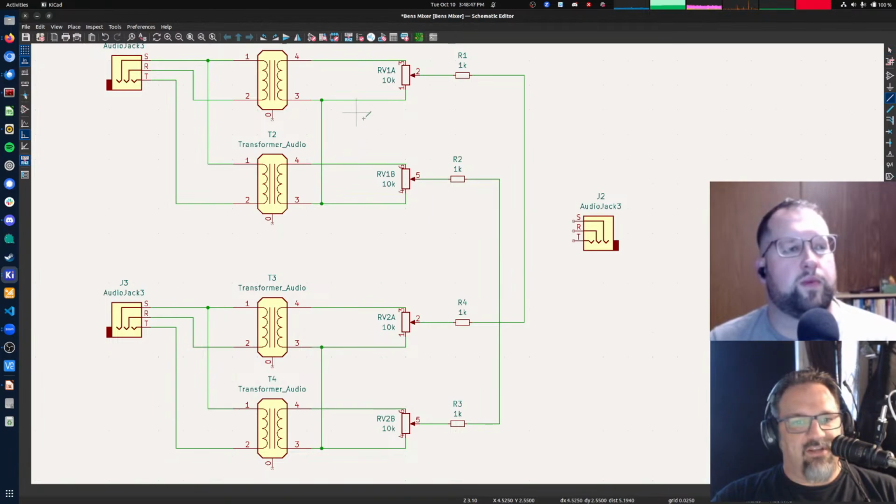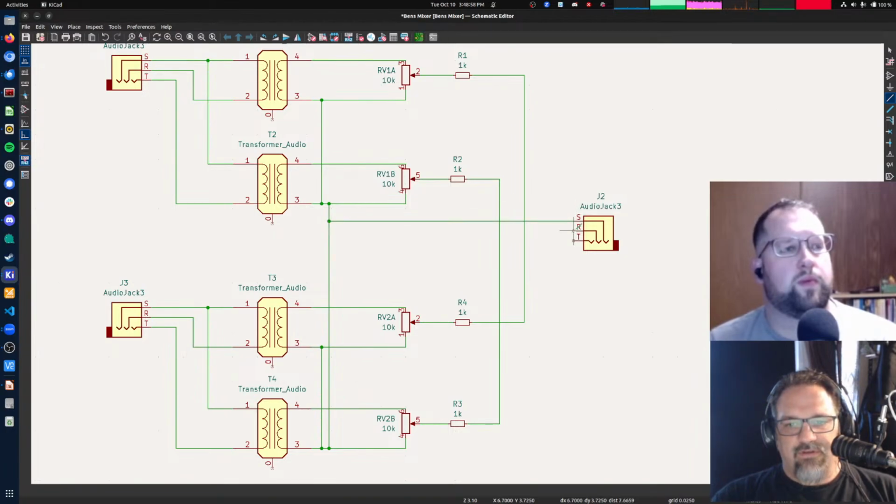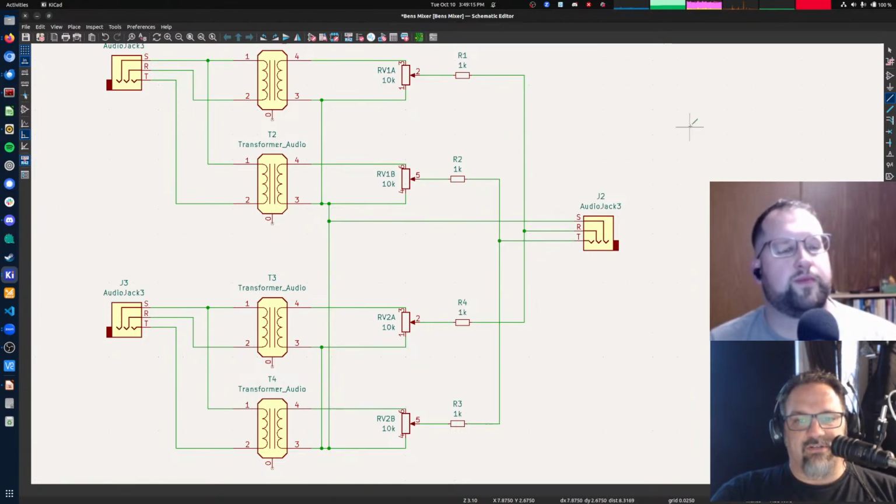Oh, and I've got to connect the commons together as well. Okay, so shield goes to the common, that's our ground. Ring goes to this one. So, right, ring coming in here goes to this transformer, that pot, and into ring. Okay. And then tip goes to that one. Okay. So, add 3 more of these channels, and that's your mixer. Does that sound right? I agree.